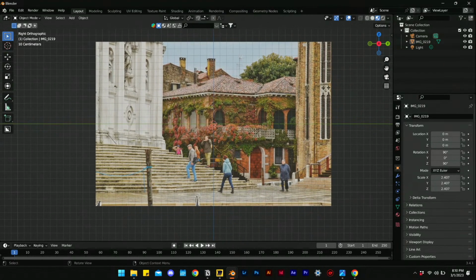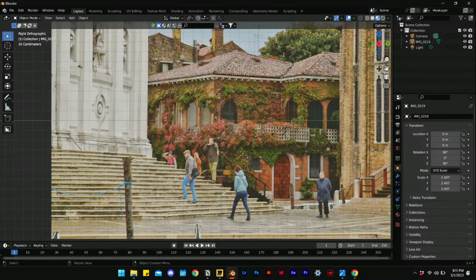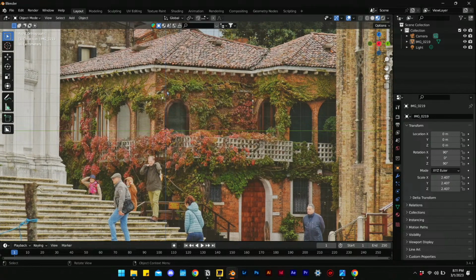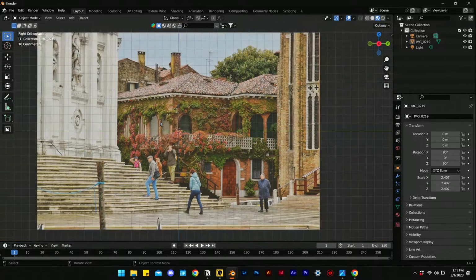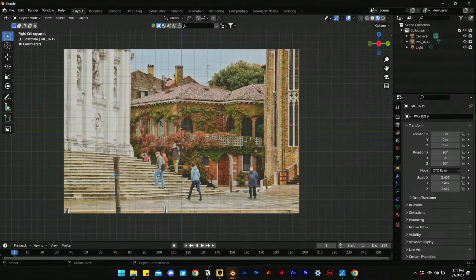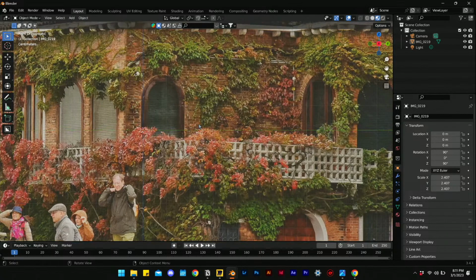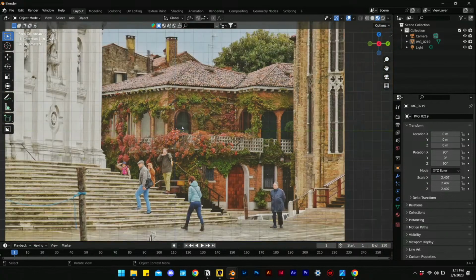Okay. Now, there's a really cool way of going about this, which is first to use perspective plotter to start getting some of that detail done, as these different elements that we want to extrude off of the building, and use the actual photo as a texture. Since it's the background that we're working with, we don't actually need anything photoreal or anything high quality. We can just work with our photo applied as a texture on a model that has a moderate amount of detail.